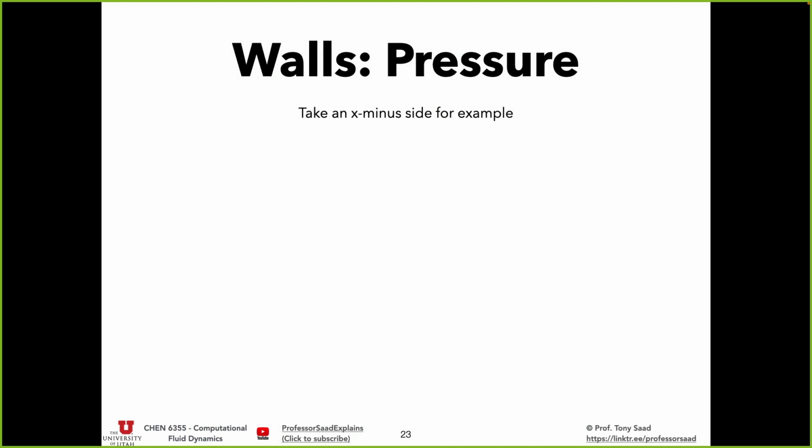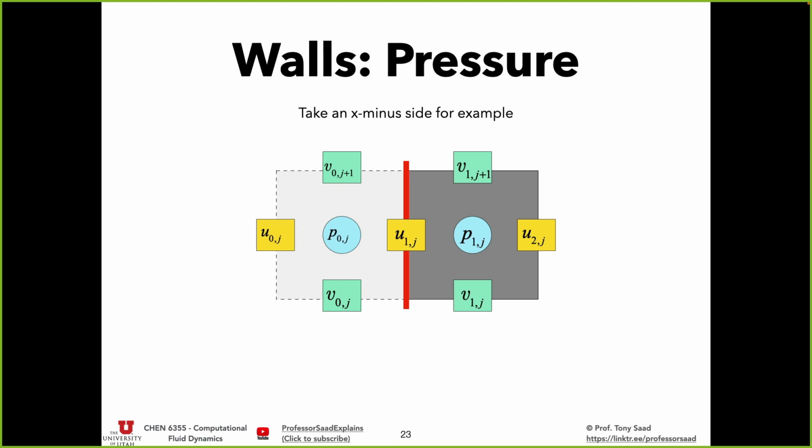So today, I'm going to show you a different derivation that is a stronger statement than what I just said. And it has to do, essentially, with mass conservation. So for the pressure equation, all I care about are the cells at the boundary where I have a velocity specified. And the ghost cells, I don't care about mass conservation in the ghost cells. They can go to hell, the ghost cells. I don't care about whatever value is in them. What I care about is to conserve mass in the interior cell.